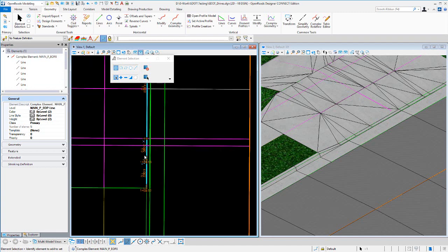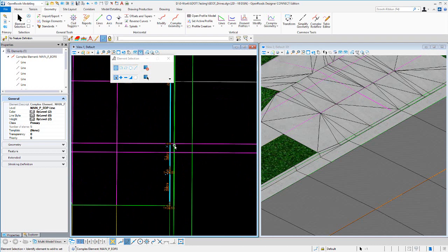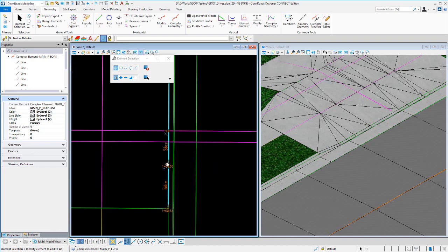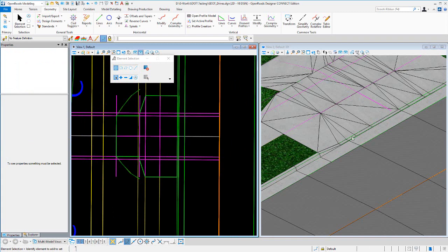Basically from this edge here, so 7 feet from the center line to that edge, you've got 3 feet that you have no curve, and then that 3 foot point is where you start that taper transition, and then it transitions for 4 feet initially. If you need to change that, you can grab that right there. All right, so that's kind of how that looks, and that taper's controlled.